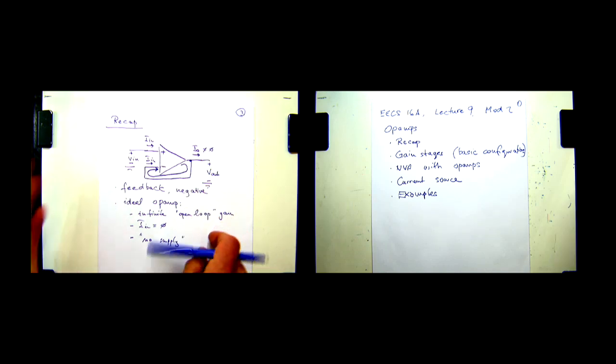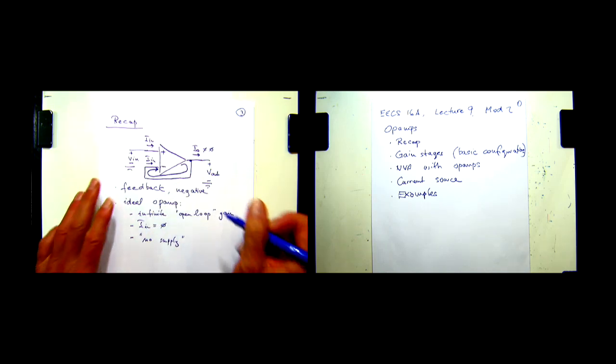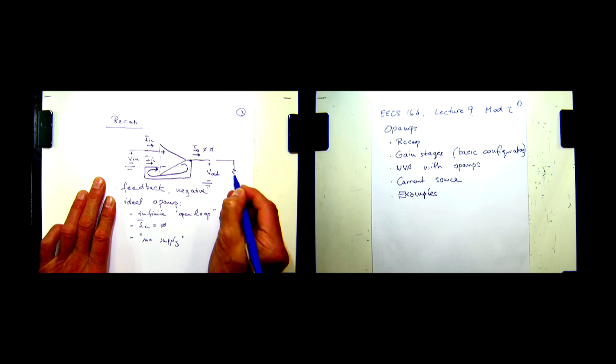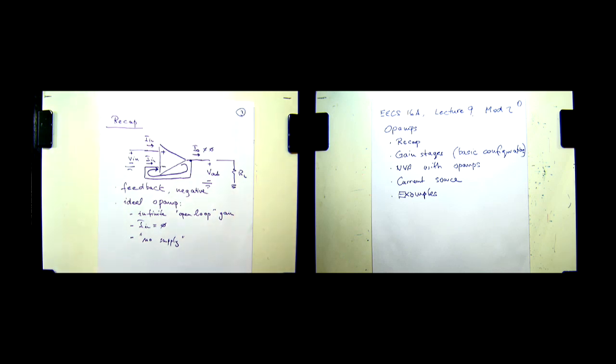Usually, it could be 0, and if I do not connect anything here, then it is 0. But the minute I connect the resistor here, then this current I0 out is non-zero. But the other two currents into the op-amp are 0, so if we add all the currents they don't add up to 0. That's a consequence of using this abstraction of an ideal operation amplifier. Just keep that in mind.